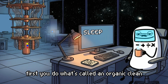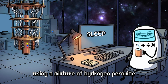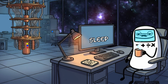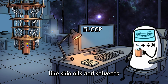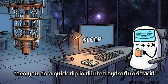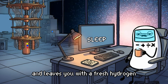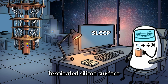First, you do what's called an organic clean, using a mixture of hydrogen peroxide and ammonium hydroxide heated up to about 70 degrees Celsius, which removes organic contaminants like skin oils and solvents. Then you do a quick dip in diluted hydrofluoric acid, which strips off the native oxide layer on the silicon surface and leaves you with a fresh hydrogen-terminated silicon surface.